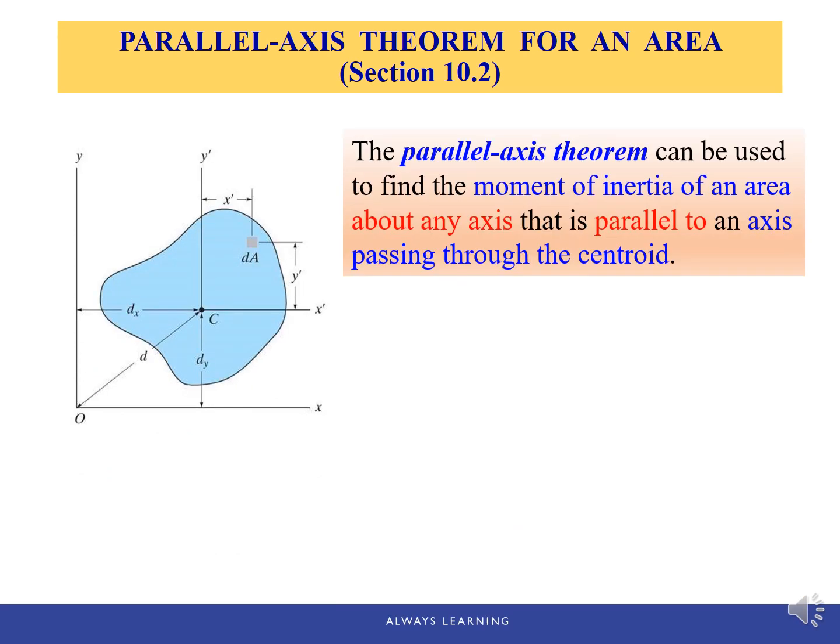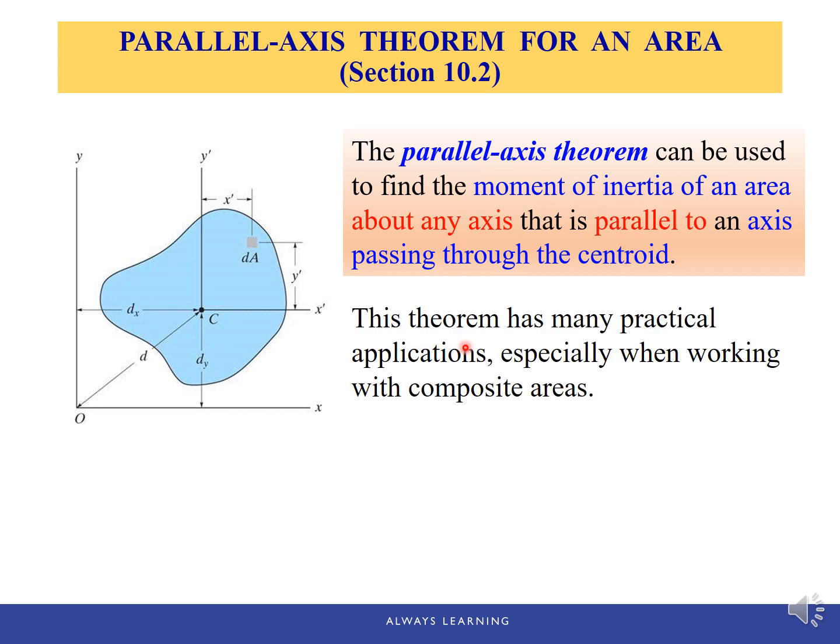The parallel axis theorem can be used to find the moment of inertia of an area about any axis that is parallel to an axis passing through the centroid, which we call the centroidal axis. This theorem has many practical applications, especially when working with composite areas.